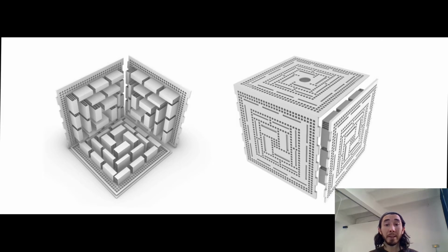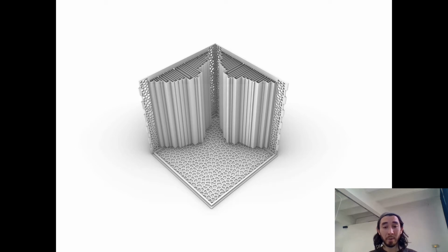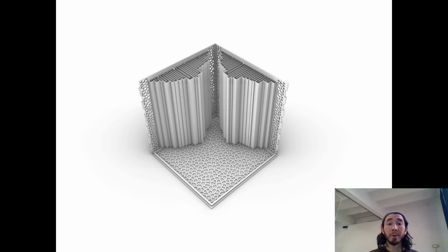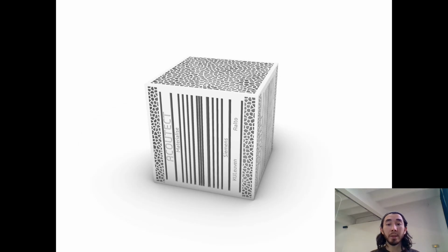Design and iteration of ducts assembly were done in Rhinoceros software using the Grasshopper plugin. On these pictures, you can see several iterations of lamp design before we came up with the last design, which allows best acoustic performance as well as optimal manufacturability using a 3D printing technique called laser sintering. This 3D printing technique allows us to produce parts with high resolution and without adding any supports during fabrication.